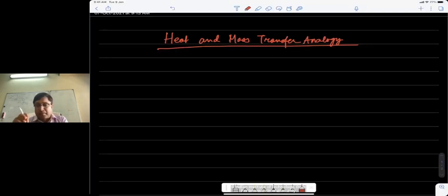So you could replace Prandtl by Schmidt, and replace the temperature by concentration, and the equation will remain the same. Moreover, what I didn't prove, but said in the last class, is that if you check the boundary conditions, they are also the same. So clearly, the mathematics says that these two concepts are analogous.